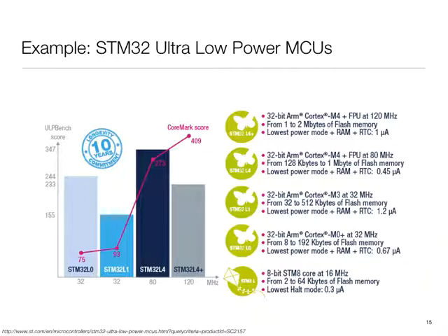SRAM is area hungry and power hungry. So what ends up happening now is that the amount of SRAM on these chips is in kilobytes. Let's say on the order of 100 kilobytes max. That would be luxury. Oftentimes it's 4, 10.